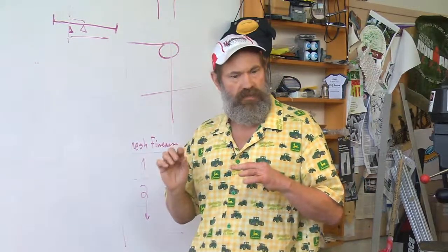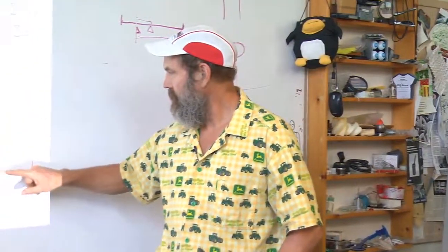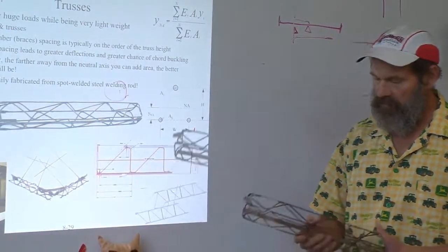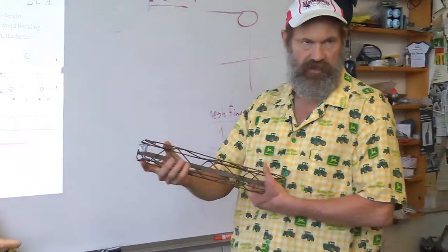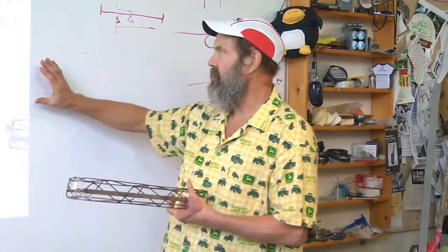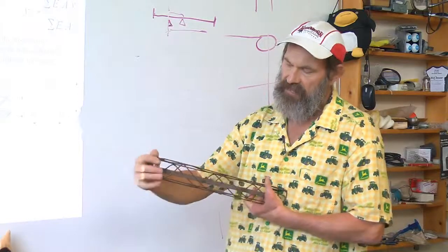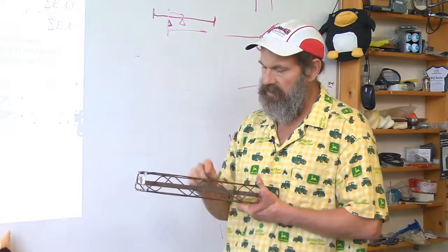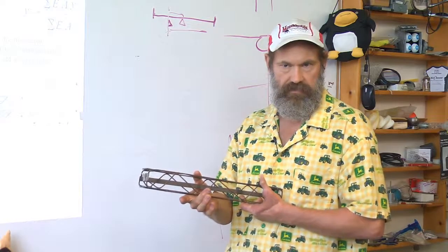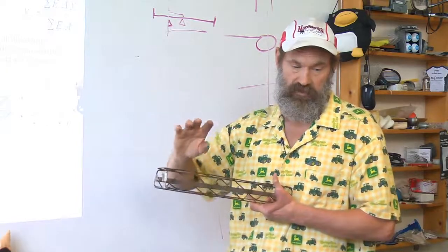It'll be important as you're thinking about the design of things like trusses, what do you do about stress concentration potentials? You may remember this shape from before. We talked in topic 3 about the neutral axis theorem, and how you can very quickly estimate the stiffness and the strength of this structure by calculating an effective moment of inertia using the neutral axis theorem. You can read about it in this part of the text, going back to topic 3.